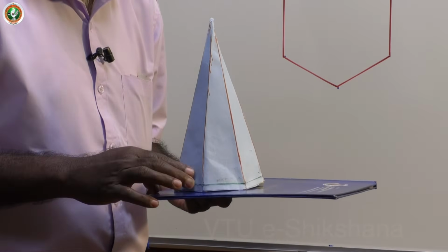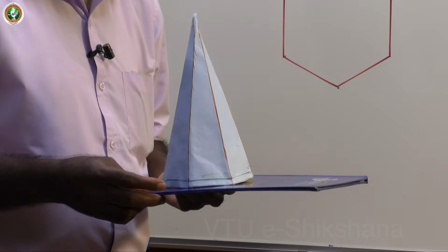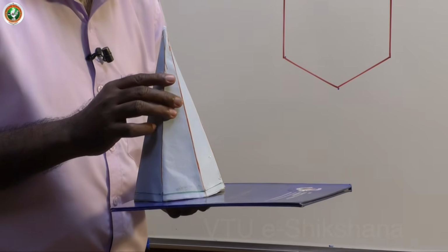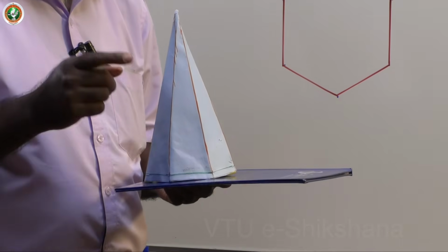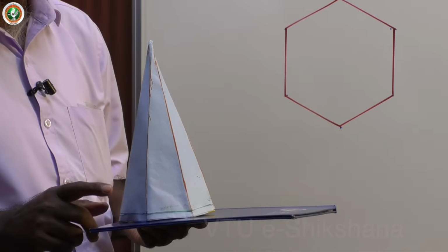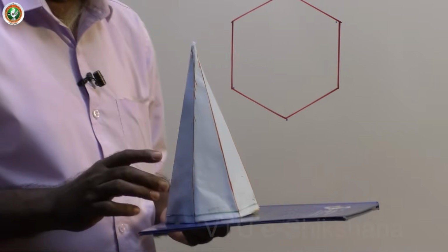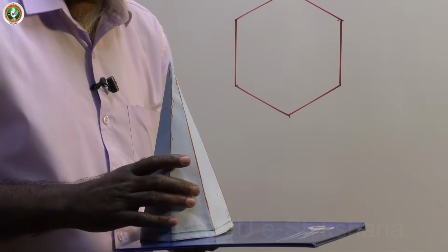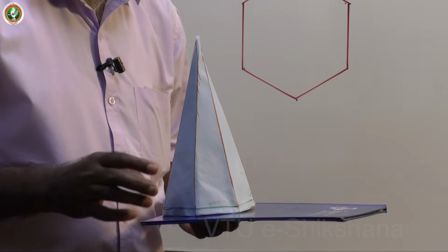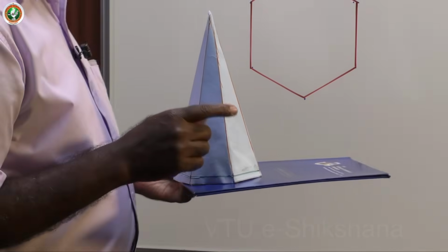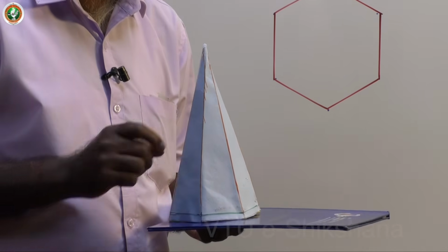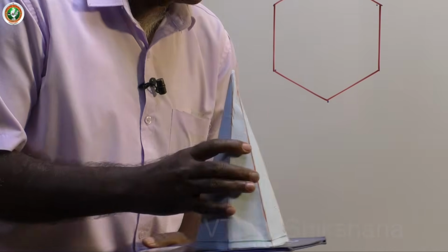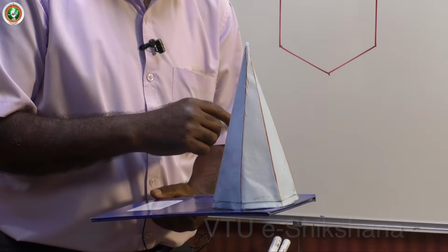These are slant edges. In case of the pentagon, we discussed the corner condition. Now let me take the edge condition for the hexagon. The same problem you can work out for the pentagon also with the edge condition. Now, the first position is this. It rests on one of its base edges on HP. So the edge to be placed on HP is always perpendicular to VP. I will keep it like this.